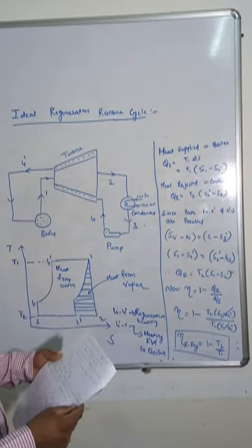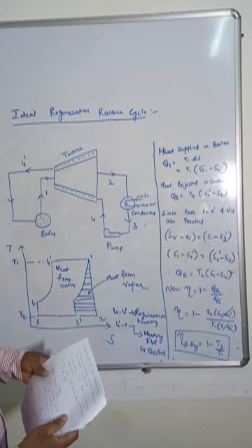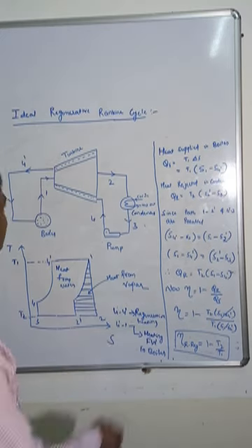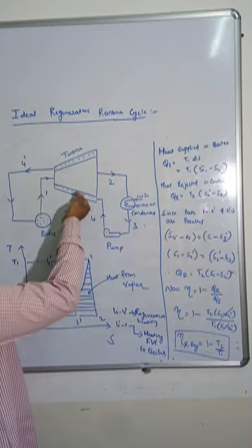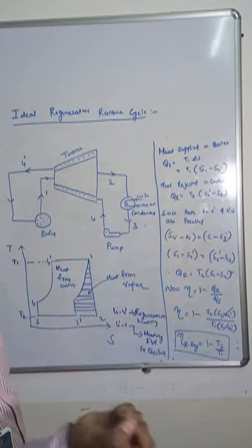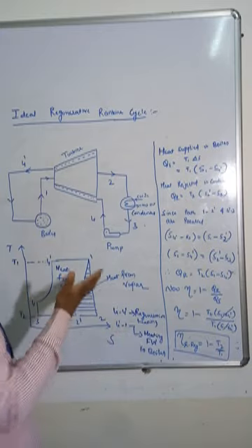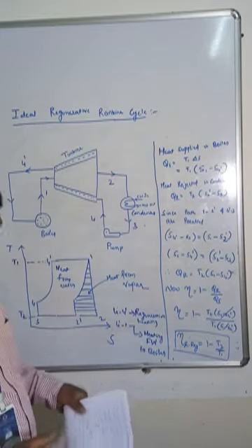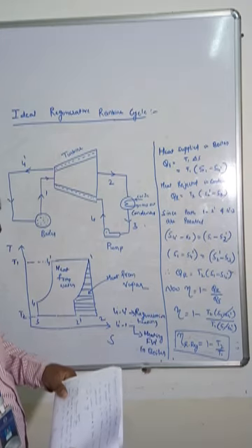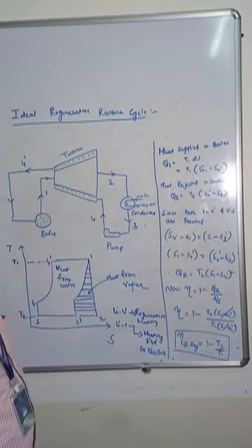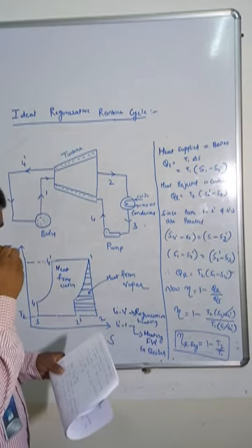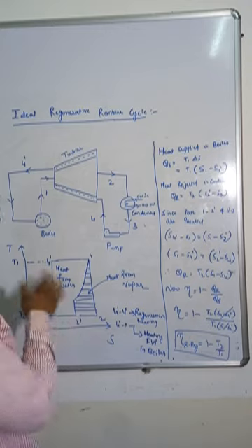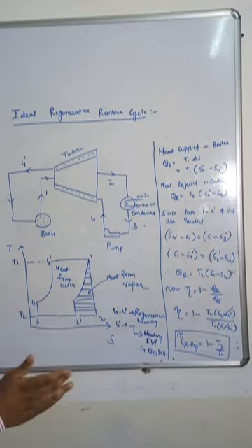So the reasons I just read out. Heat transfer in the turbine casing cannot be obtained in a finite time, because within a short time the pump is pushing the water and the water is coming out. I don't know how much heat is transferring; a finite amount of heat will not be transferred. A heat exchanger in the turbine is mechanically impractical, right? It will also increase the moisture content in the steam, so again that will cause more and more problems.